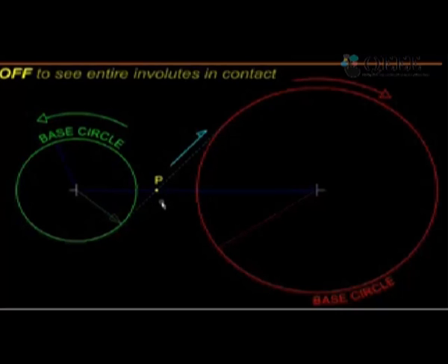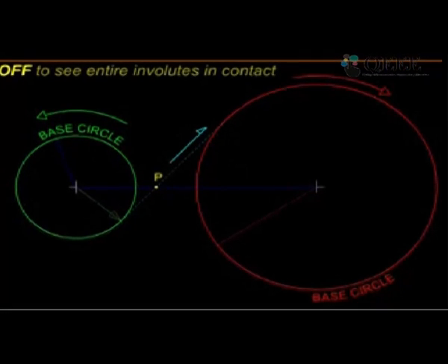There is a simple trick to achieve this, and that is, we will take a point P on the belt and put a pencil there and draw a shape or a profile or an extension on both the pulleys simultaneously. Since both these extensions or profiles are drawn by a common pencil, they will definitely make a contact at that point, and so the contact will be maintained.